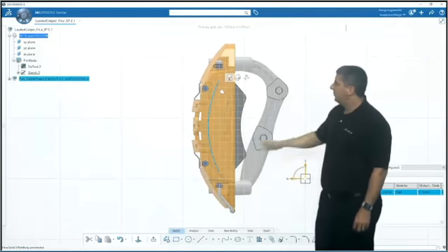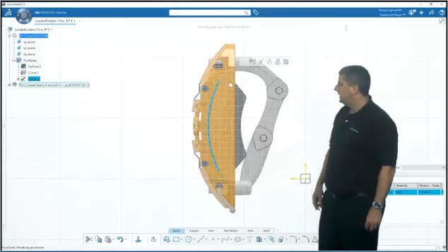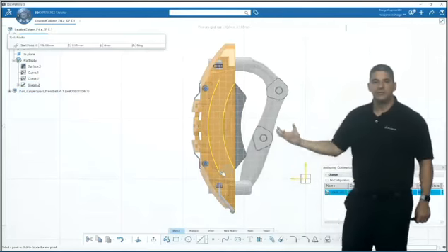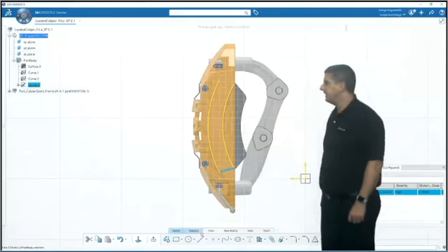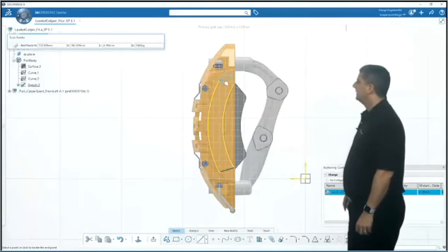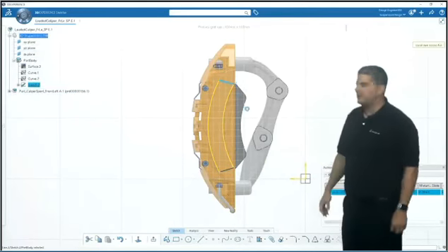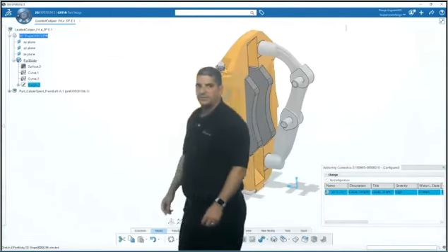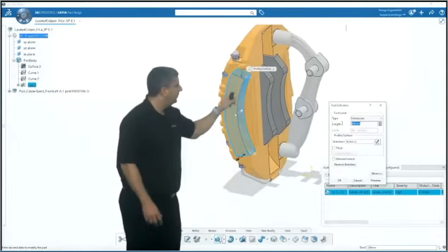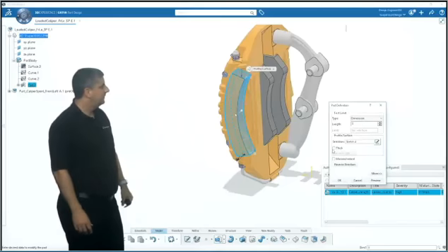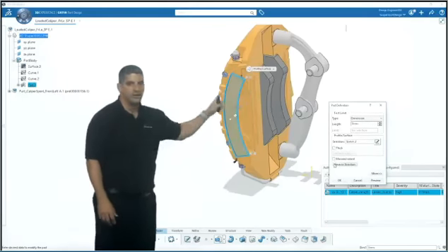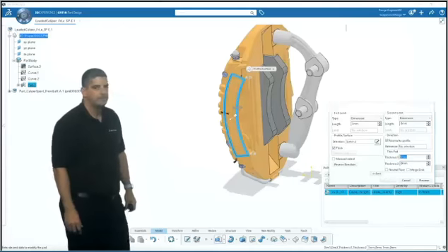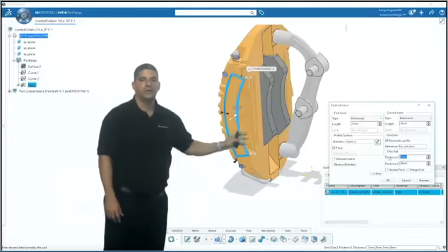We're going to project in some curves into the sketch plane. We're going to close them off so we can build this part, kind of tie it to this. Pretty simple, basic part design stuff. We're going to go in and define the direction for that pad, and we're going to make it more of a thickness here, so we'll have a little bit of a hollowed out piece in the middle. Pretty basic stuff.